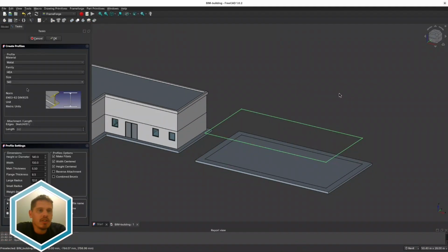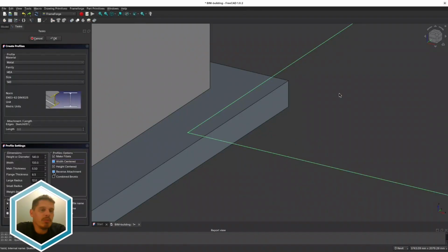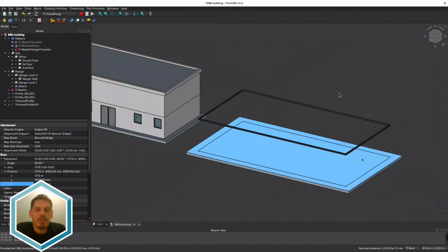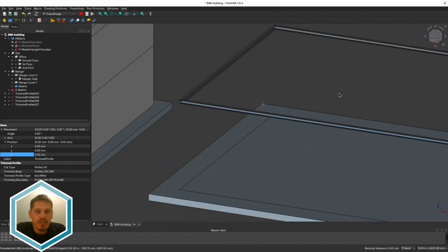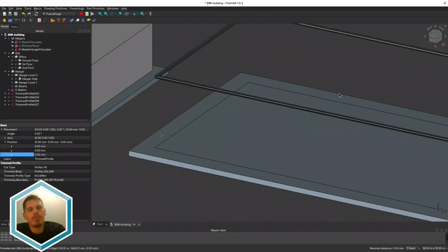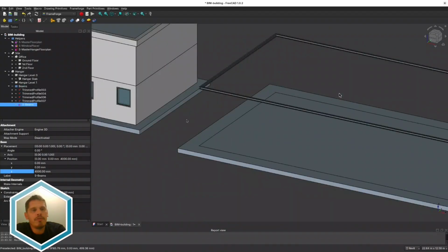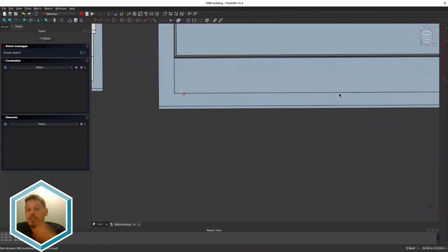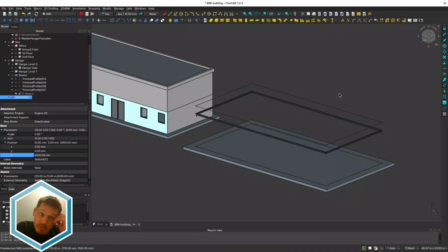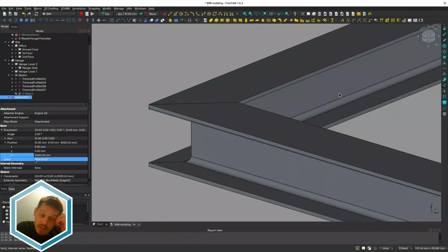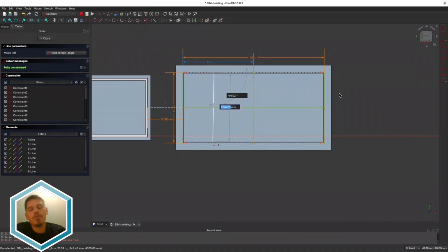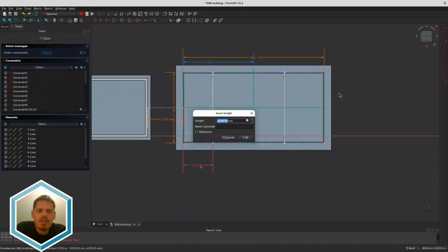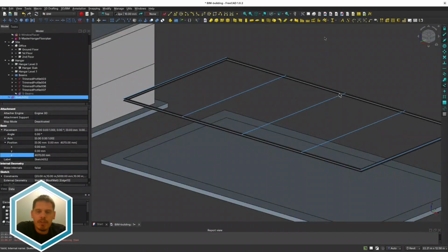I love using it if it works, but if it breaks, I just use dimensions, and you can be dynamic with dimensions as well. If you make a variable or you use a spreadsheet and you just put the dimensions in there, it's not that hard. Here I'm using a different workbench. FreeCAD has a whole bunch of workbenches. The FrameForge one, in which I also use a sketch, and I put a, what kind of beam was it again? I think an HEA 100 or 120. No, 140. An HEA 140 beam. And I have 5 of those and I space them 5 meters apart.